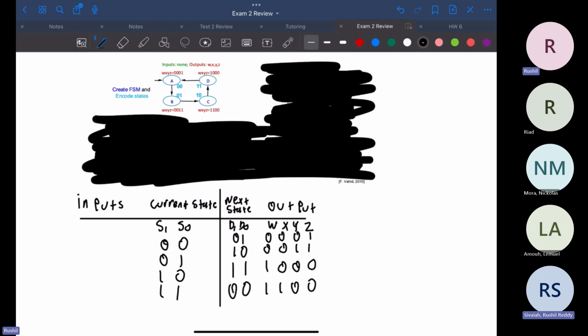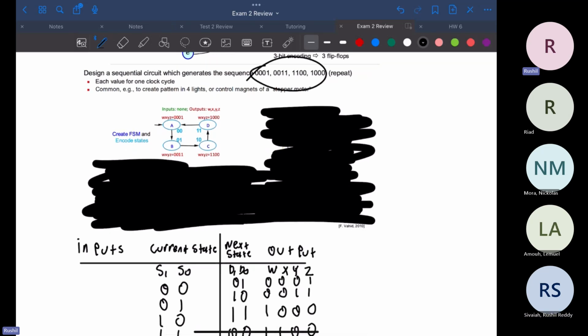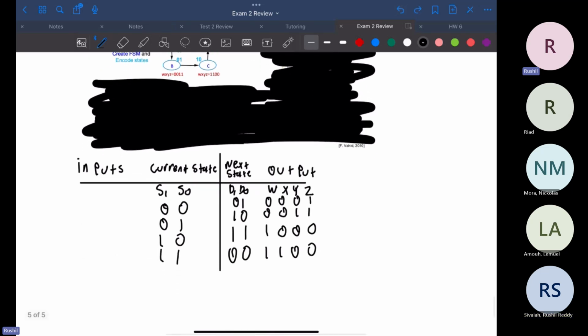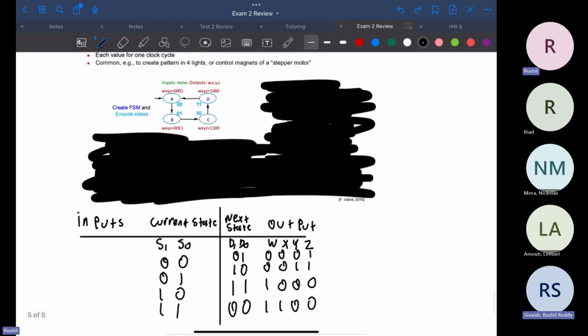All right, any questions how I got here? Because this is the easy part. Output. I pulled this straight from right here. Isn't that given? Yes, it's given. Those are your given values. It's also right here, so you can transfer that into here. So since we know that our current state is 0 0, we copy whatever that output is. And for the next one, 0 1, we copy those values, and we go on for every single possibility.